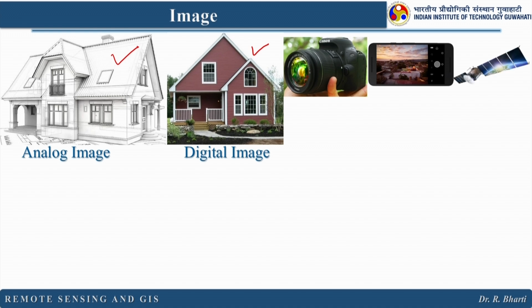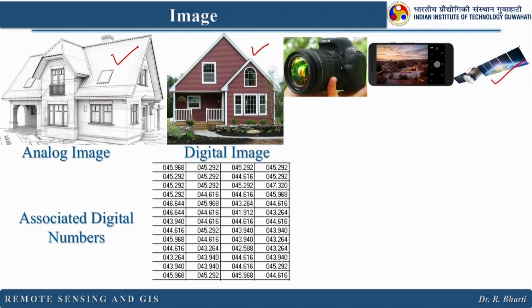object. And now in remote sensing we always refer to sensors. Here is one example of a spaceborne satellite which has various sensors, and those sensors are sensitive in different wavelength regions, and then they generate images, and those images are basically numbers. If you zoom any image, even this image, you will find small pixels, small square boxes. If you zoom, you will find those pixels growing bigger. Those pixels, as referred to in remote sensing, are nothing but digital numbers. Just for visualization purposes, we have assigned some color to those numbers based on their intensity, and we are able to see the images.